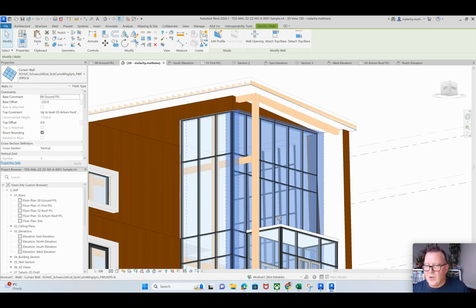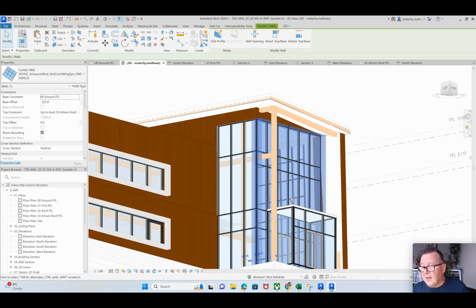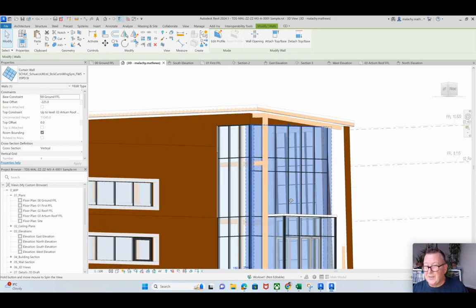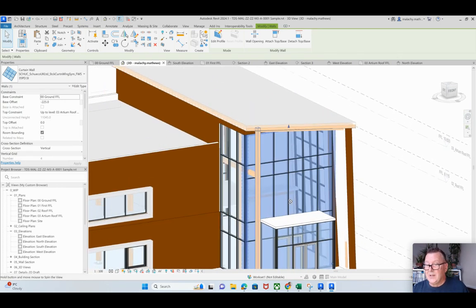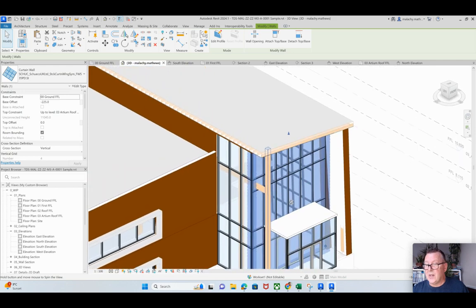And remember, I'm talking about moving this column up closer here as well, so that it'll be supporting that beam. So I think the cantilever would work there in that case. I might be able to take out that beam altogether in one sense as well, and just rearrange the joists into a ladder or something along those lines, or even take the roof back a little bit so that it's not sticking out as far as it should be.